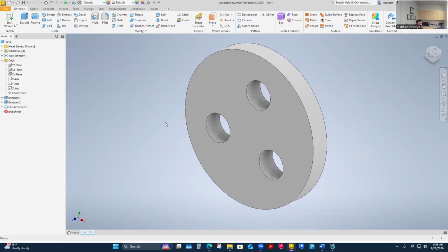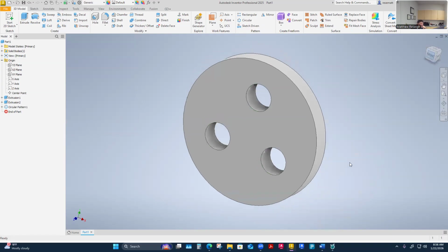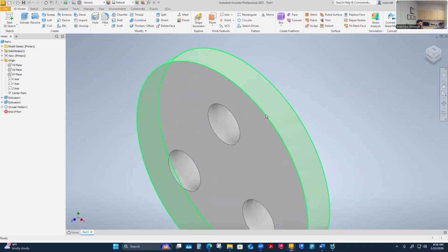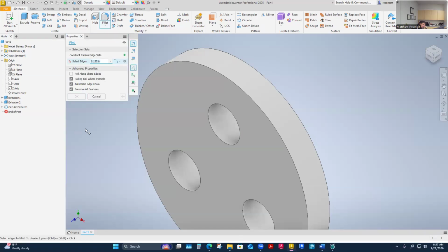And then it just does a radius on the front edge here. Here's my front surface. And then it's just going to radius this corner here with a fillet radius of 0.0625. That's 1/16 of an inch. So that's just the normal fillet, right? Remember, there are 3 different types of fillets. I call this one my normal fillet, my simple fillet, which really just gives you the option to enter a fillet radius here, which I need to change to 0.0625.